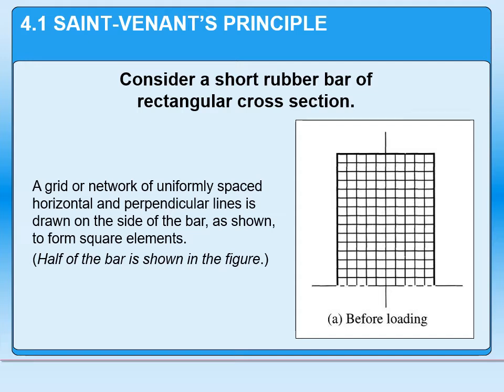So here is an example of a situation where we can easily see changes in the distribution of strain, which will give us information about the distribution of stress. In this case, we've made a compressive specimen out of a rubber material. Rubber material is selected because it's very elastic and we can significantly deform it without failure.